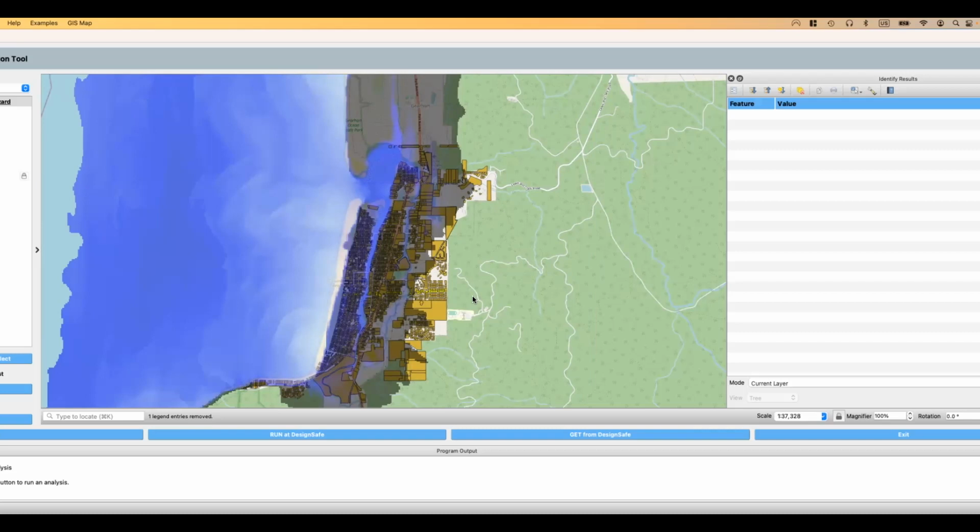Yes. Well, you have to convert it into SimCenter format first. So if you write a script that takes, say, the FEMA grid, and puts it into that same format I showed previously, where you have the event grid file that has each ground point, lat long, and then each ground point is its own CSV file with different columns for however many intensity measures or attributes you have, you can use it here.